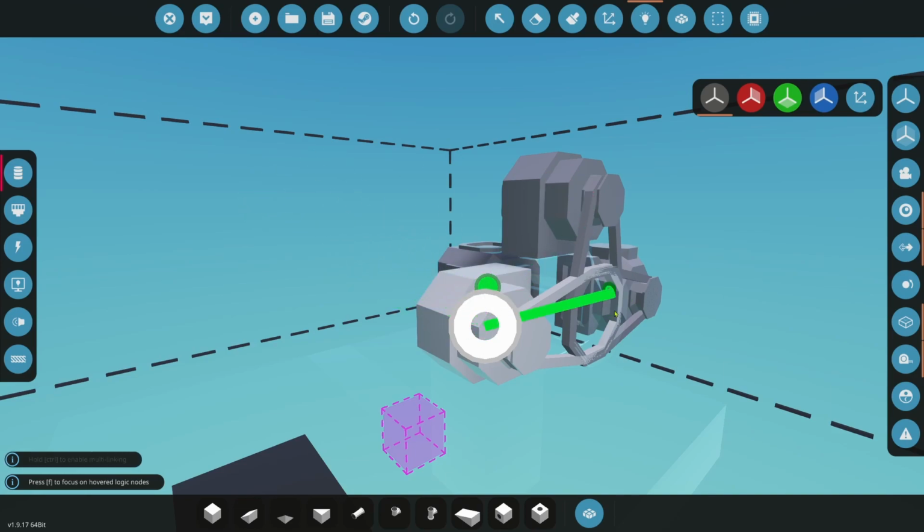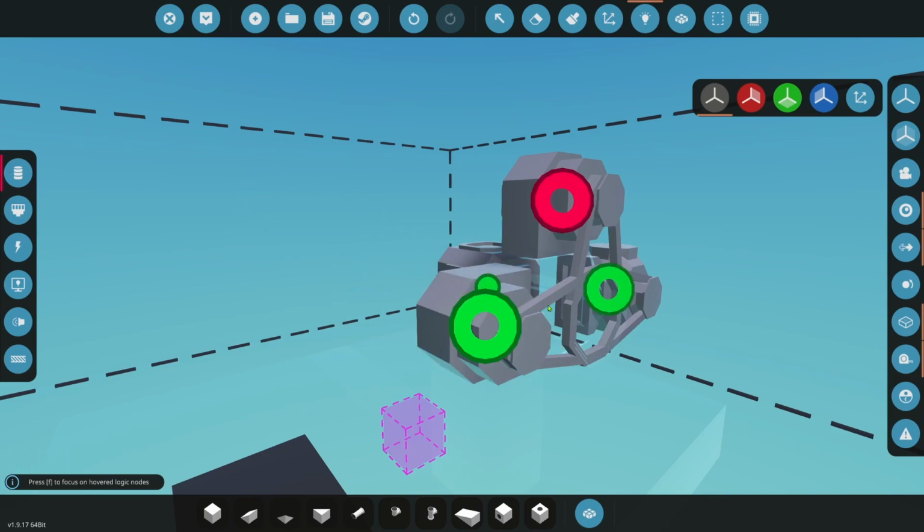On the alternator here, you see we have clutch pressure. So what that does is this belt's going to turn and we're going to decide how much pressure we want so that it transfers more or less energy. Now, we don't get anything for free. If we use a 1 value, which is the max number on this, it's going to be producing as much electricity as possible, but it's going to be putting load in the engine. So for example, let's say that we don't need all that electricity. Let's say we're barely using electricity. We might need a small number like 0.1 clutch will give us plenty of electricity. That allows the other amount of the engine power to remain for actually powering our vehicle. So that's important to know.